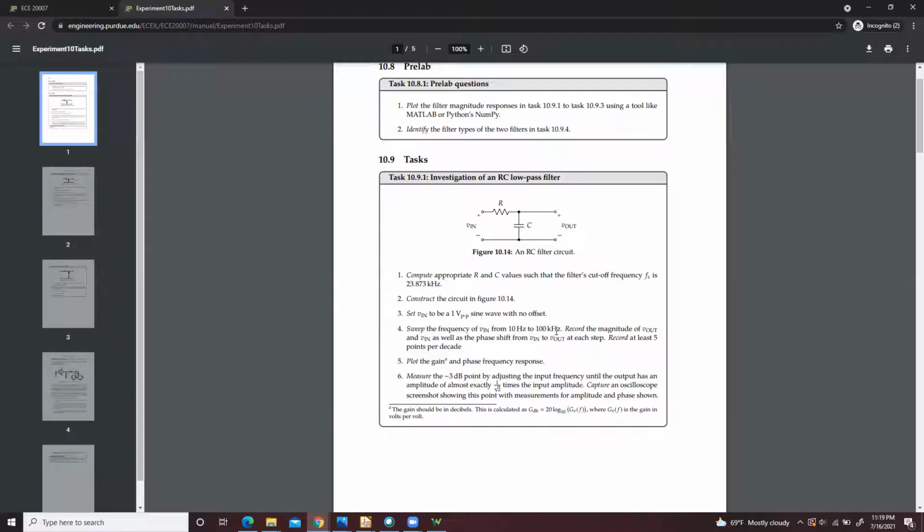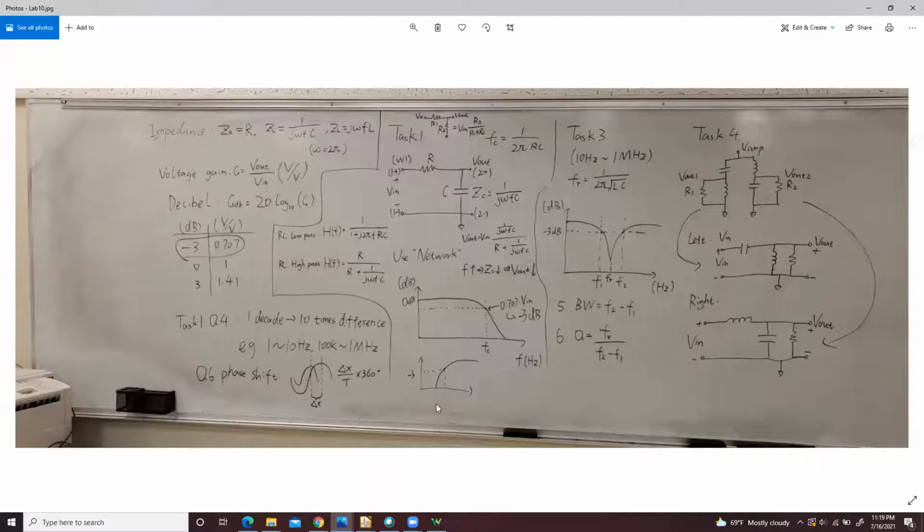One way to do this is to manually change the input frequency with the wavegen, record the data and make a data table. Another, easier way is to use the network function in the waveform software of your AD2. I will show you how to do this later.